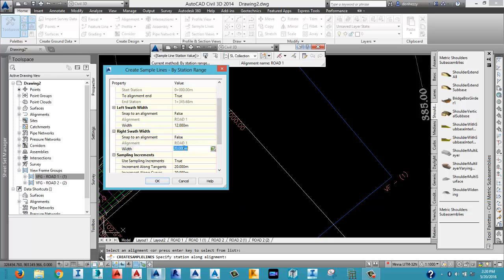One thing about this swath width is that it's just like your right of way. Your swath to the left and your swath to the right is just half. This is my center line. If the right of way is 12 meters, I always add a meter to my swath width. My swath width is my half ROW plus 1 meter. I don't know if you're getting it.